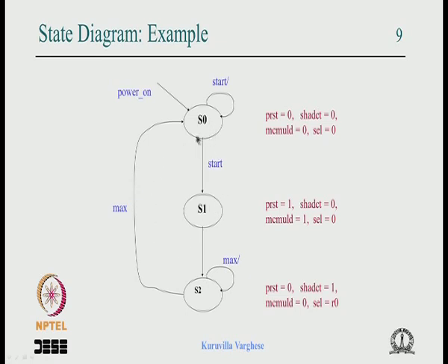And as I said, normally, like in software, you come to a state where everything is inactive, then wait for some signal, then you come to another state, initialize everything, then come to a main computation state and iterate through many clock cycles, and when the computation is done you go back and wait for the next operation.